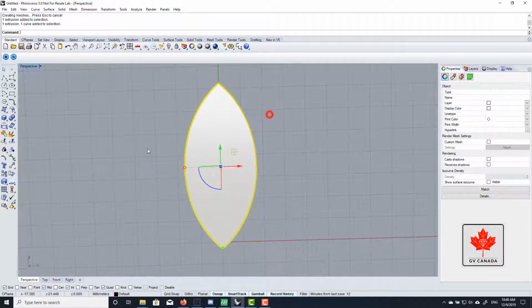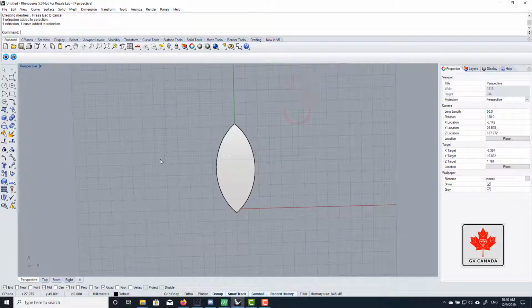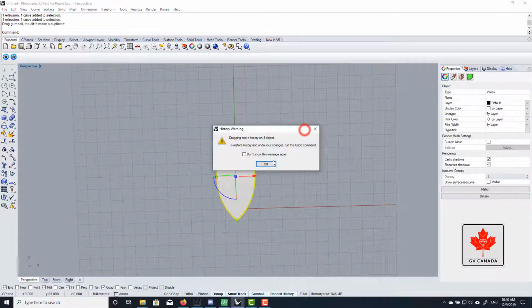And what I'm going to do is select everything. So remember, selecting in box select, if it's dotted, as long as it's selecting a piece of the object, then it'll select it. If you're going the other way, from left to right, the whole object has to be within the box to select. And then bring this down.